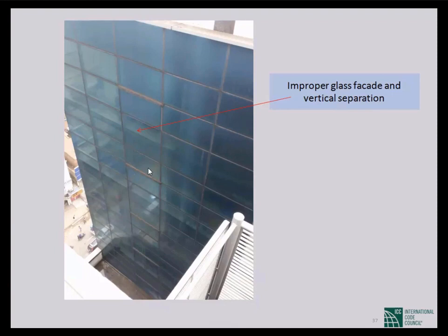So there is some separation between the first and second floor, because that table will give you vertical separation and horizontal separation. But in this case, you see the glass tower, which is very common in Dhaka, particularly in the Banani and Gulshan area. There are a lot of huge high-rise buildings with glass. Almost all buildings don't have fire separation. Almost all have zero fire separation. This is very dangerous. That happened in the FR tower with the zero separation. So you have to be very careful.